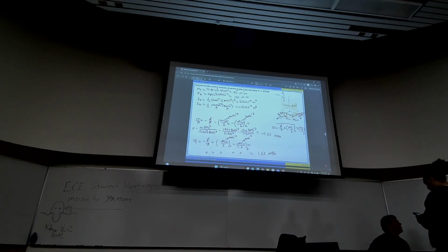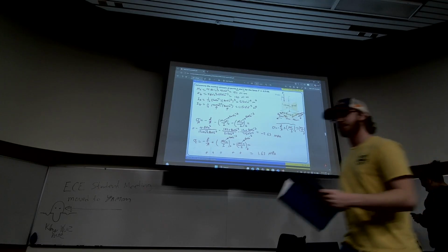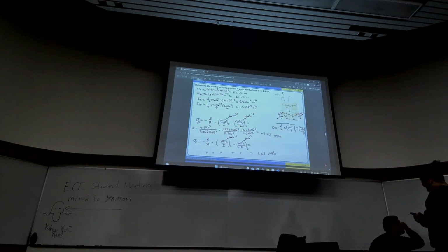That was the idea. Just make sure once you found the force value, you determine whether it's tension or compression. If it's tension, then pick strength in tension, otherwise pick the one in compression. Yeah, that's where I ended up messing up. You fix it. You're fine. You just confirm.